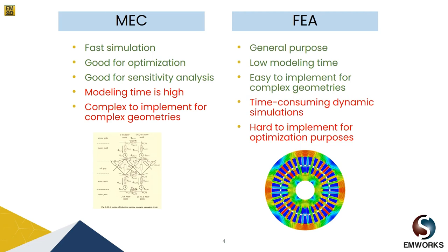But using finite element analysis for optimization is complex, right? Because for optimization purposes, we need to do dynamic simulations. And when we want to consider a fine time step, the simulation time is high, and consequently, it's hard to implement the finite element method for optimization or sensitivity analysis purposes.